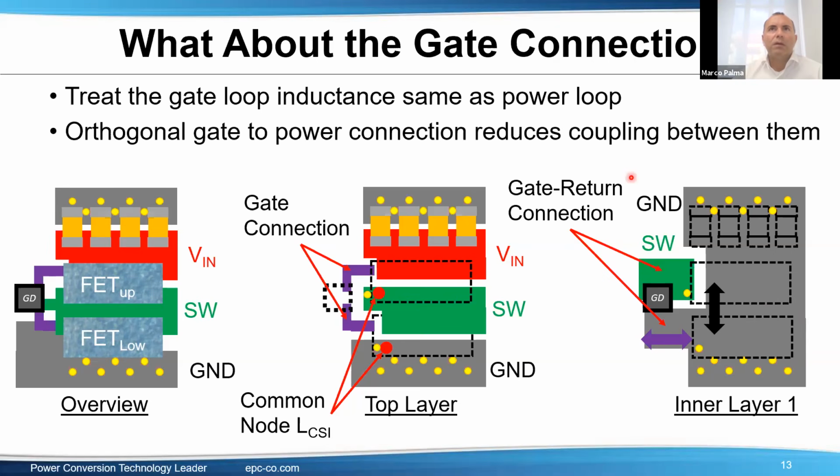Remember one thing that's really important when dealing with GaN FETs: always use a gate driver made for GaN FETs. A typical GaN FET gate driver has two outputs. One output is to switch on.